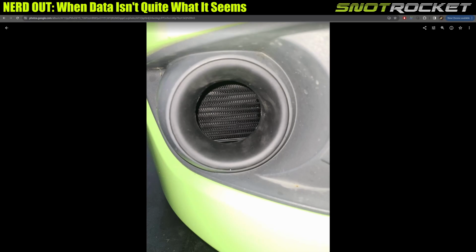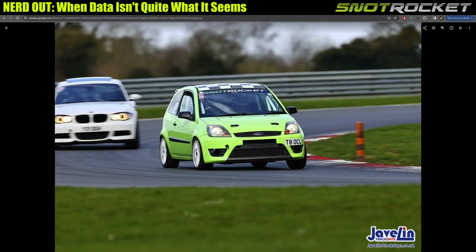And when you look here, this is the view of the oil cooler through the duct that I made on the fog light on the front of the car. And going back here, you can see that it's behind this duct hole here on the front of the car. So that's this setup. We've got the oil cooler. It's thermostatically controlled on the sandwich plate, and it's not massively ducted at the front. It's got a hole, and that's about it. But this was the first test on track with this package. Anyway, right, so going back.